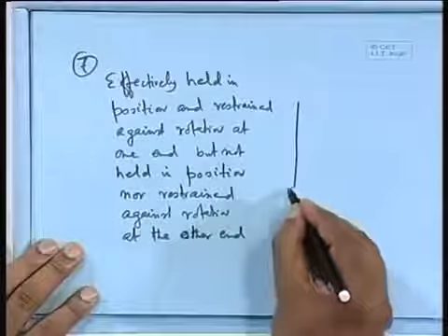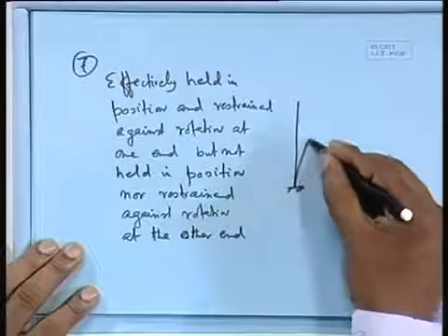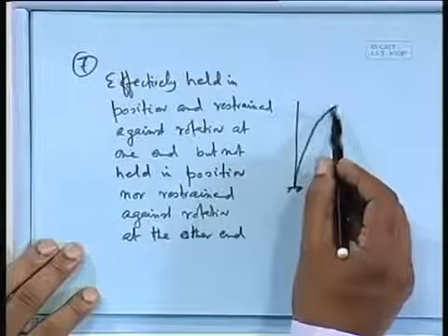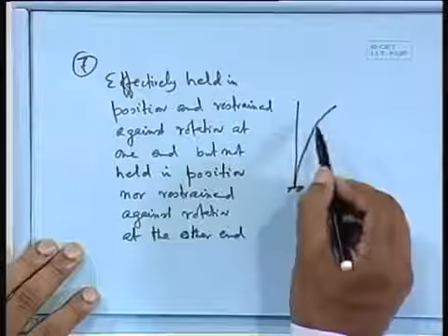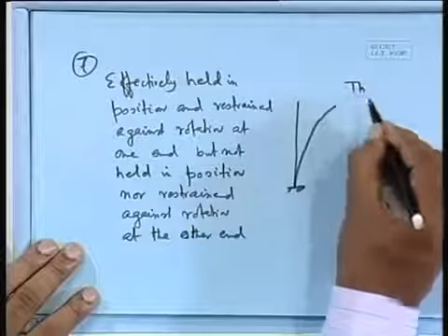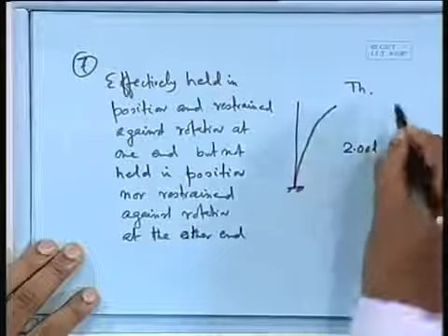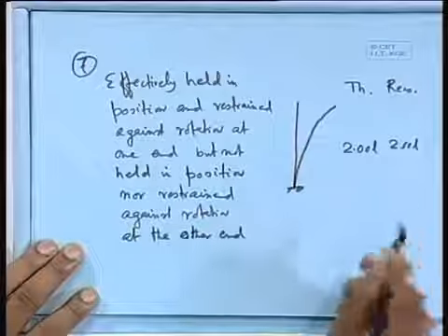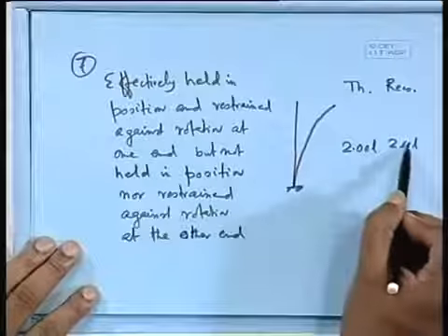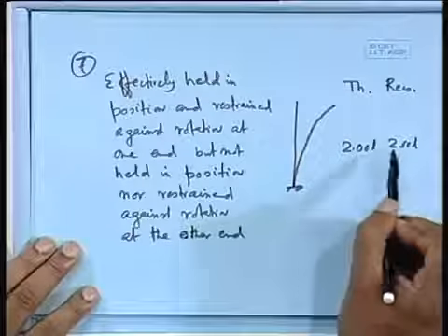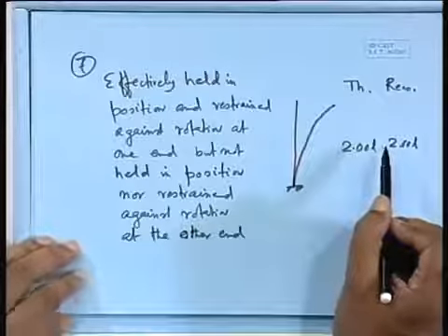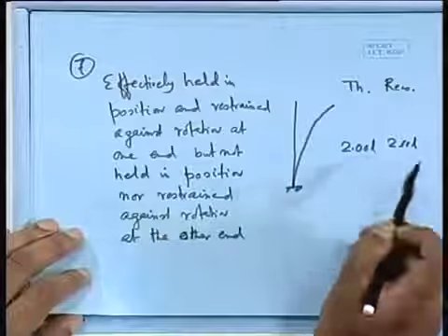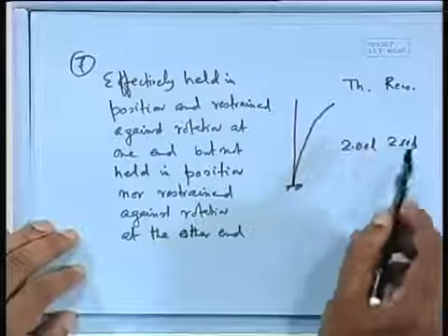So we are talking like this, as if it goes like this. There is no such limit, neither in movement nor in rotation. Your theoretical value gives 2L, and the recommended value also gives 2L. So this is the maximum we can have, 2L, that means twice the unsupported length, for the cantilever beam, and the minimum is 0.5L. So it is very, very important what the effective length should be.